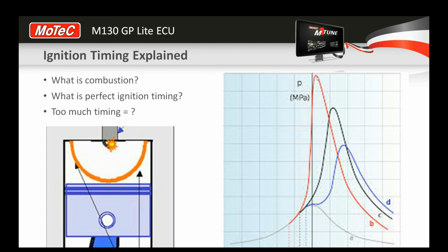I know you can't see that for normal tuning. Universities and OEMs have equipment like this, but for most of us, we're either doing it on the road or with a dyno at least. The dyno is really the time you need it for ignition tuning. You can do a lot of general fuel tuning and other tuning without a dyno, but when it comes to ignition timing, you really need to be able to measure the small gains that are achieved as you advance or retard the ignition timing.